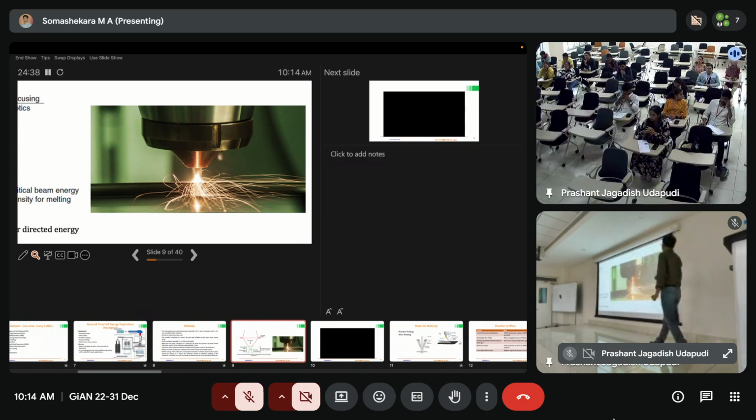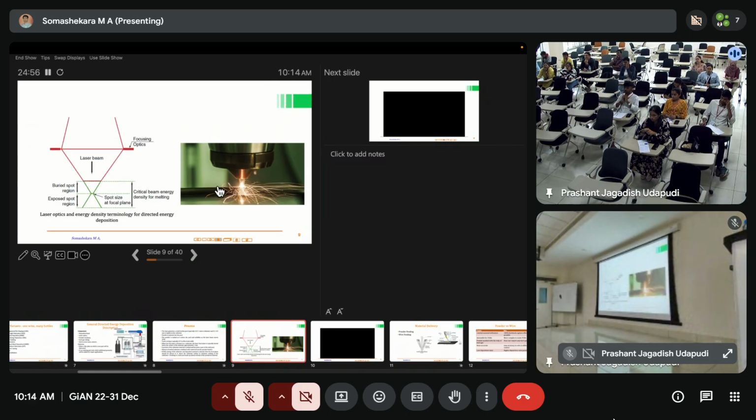The powder and the laser both come and interact at this surface, and you're melting it, and then your laser moves away from the melt pool area, which is nothing but you moving your bed, so that you can create one layer, or repeat the same layer by layer, and then you get one full layer, right?